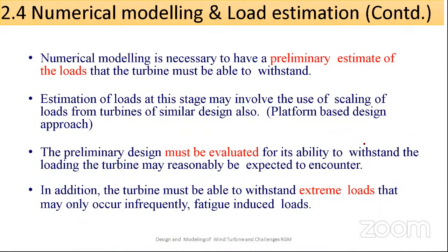So, numerical modeling. First a preliminary estimate of the loads, then the numerical modeling; simply, we cannot design without the preliminary load estimations. Estimation of load at this stage may involve scaling of the loads from the wind turbines. The preliminary design must be evaluated. Once you have done the preliminary design, you have to give it to a third party to evaluate. Without evaluation, it will not be valid. How do you evaluate it? You have to give it to the third party. And in addition, it has to withstand the extreme load conditions.